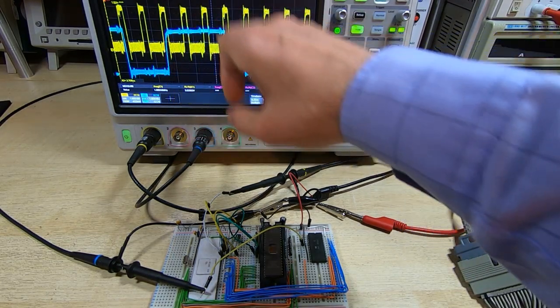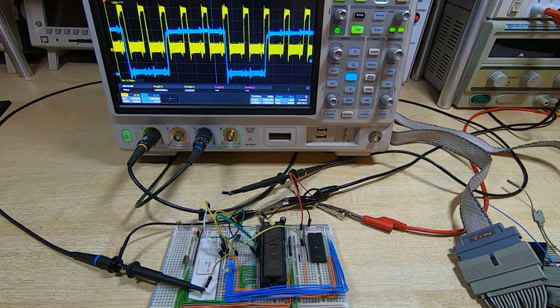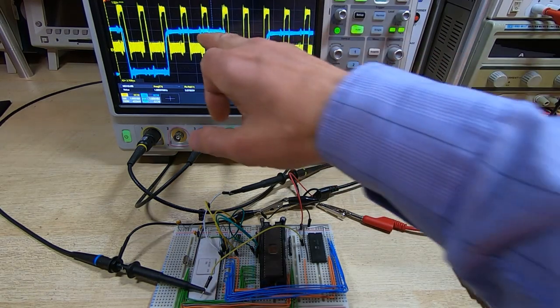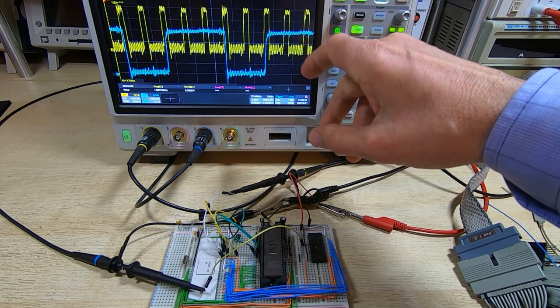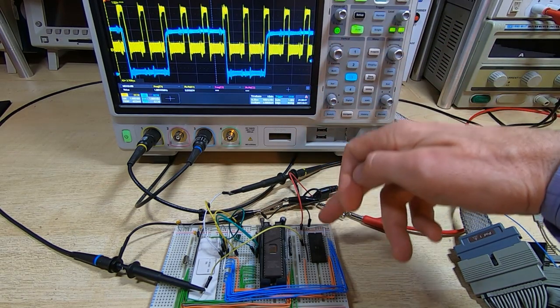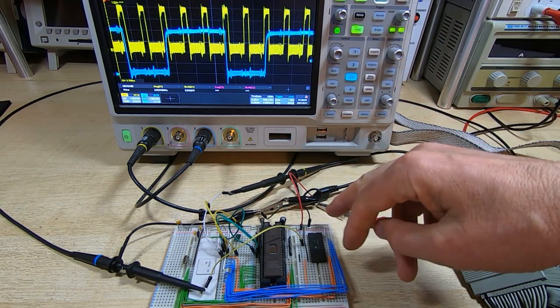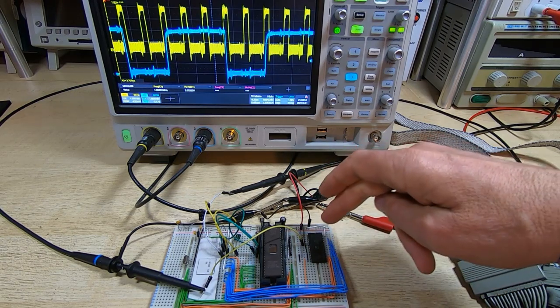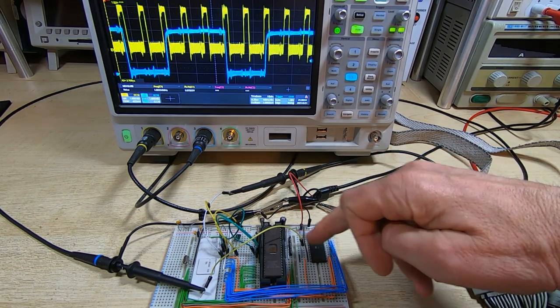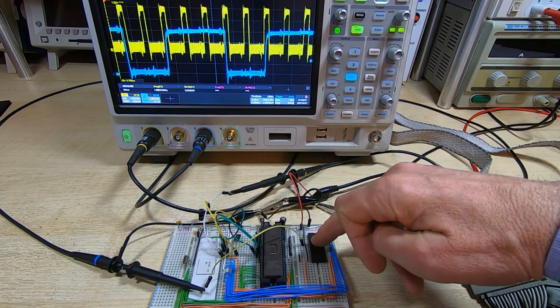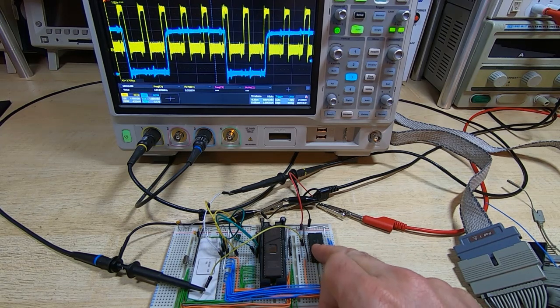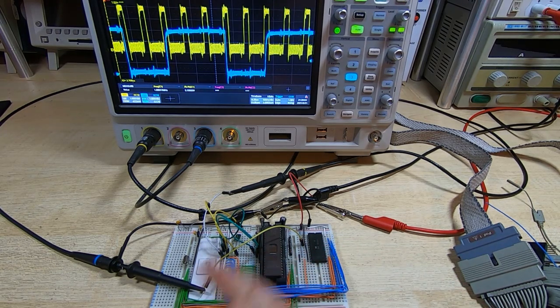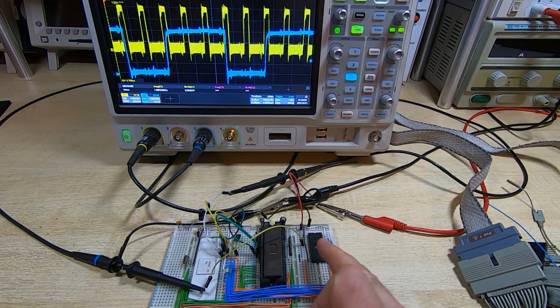You can see the blue trace is cycling up and down as we would expect, and this is in response to us writing the value of 3 followed by 4 followed by 3, etc. to the port. So that's now working, and in the next video what we'll do is we'll hook up the logic analyzer to the in-out port chip, and we'll see how the signals look on that particular device, and also why we will need to select a different clock if we want to look at the interaction in more detail.